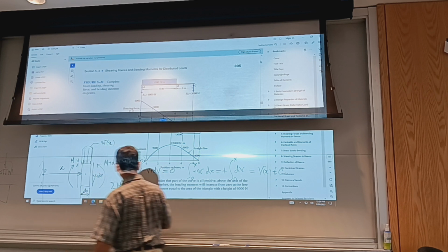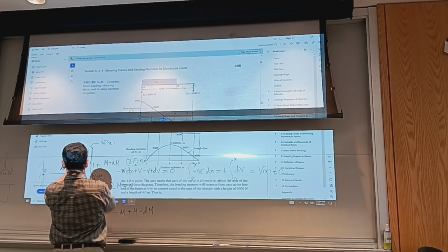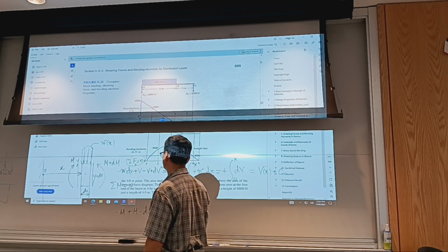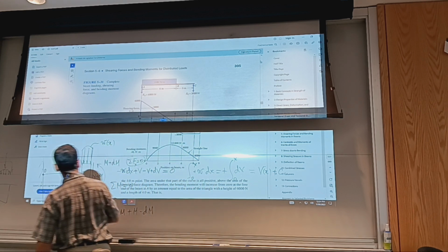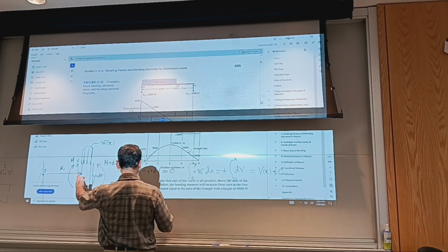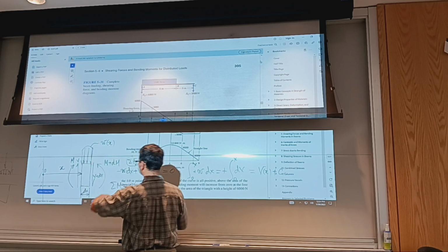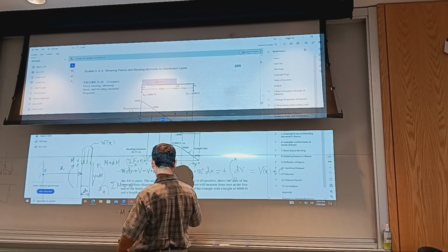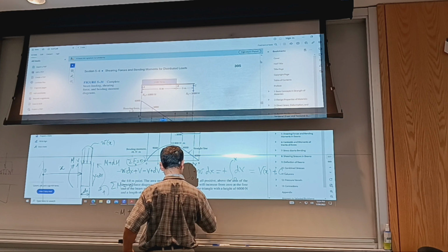All right, and then I also have to include the moment caused by these two forces. Actually, it's better if you do it about this spot. So it's going to be times, and it causes a positive moment. So I have negative, assuming positive for moments this way. So it's going to be negative V plus dV, okay, times dx.